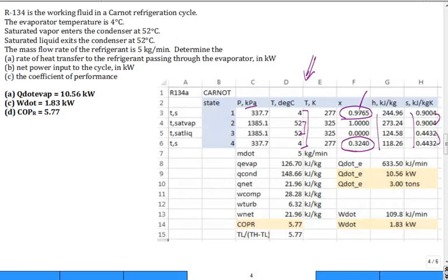Okay. Let's go ahead. We compute our Q's. Notice I went ahead and left all of my Q's positive. I know that when you do Q net, you have to take and subtract 1. True. And so what's being rejected in the condenser is greater than what's being absorbed in the evaporator. And so it's 21 net out of the cycle. The work of the compressor, work of the turbine. So it's a net of 21.96 into the cycle of work. Just opposite of our power cycles.